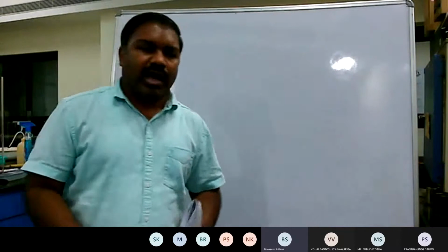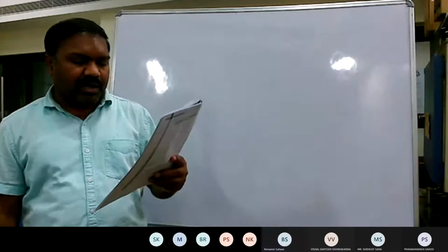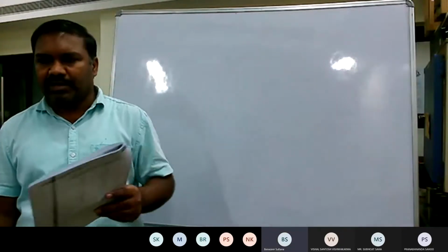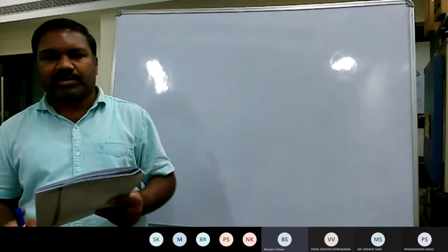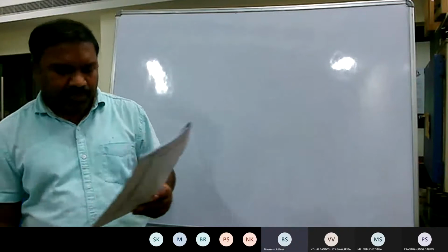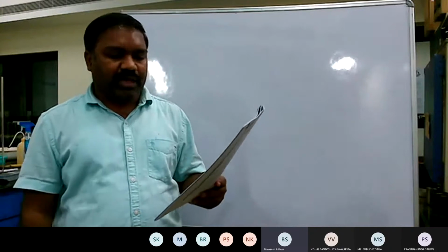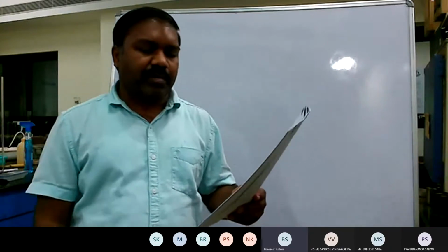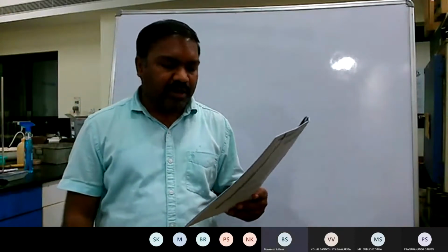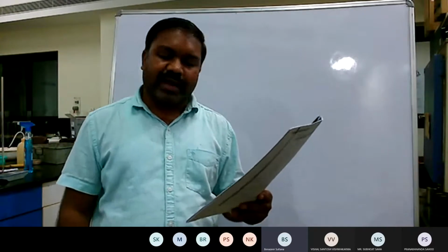Is it clear? As the element is subjected to the shear stress, the applied 100 kilopascals in the axial direction and 40 kilopascals in the lateral direction are no more principal stress components. Rather, you can designate them as sigma x and sigma y. Now, you need to draw a Mohr circle to determine the magnitude of the major and minor principal stress, the stresses on a plane inclined at 25 degrees to the horizontal, and the maximum shear stress and the plane on which it acts.